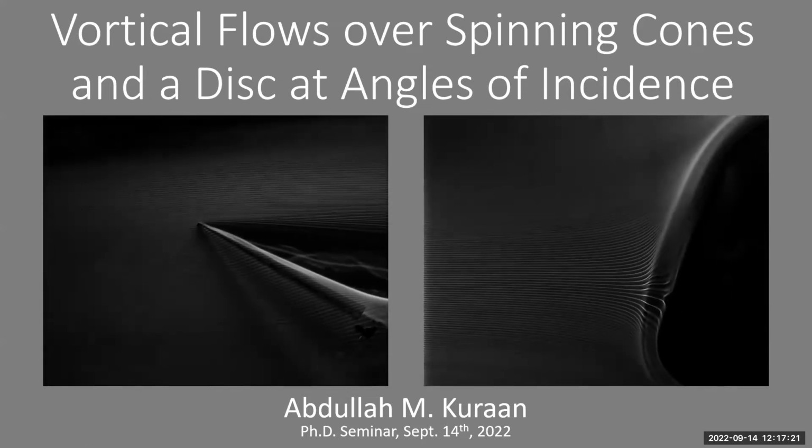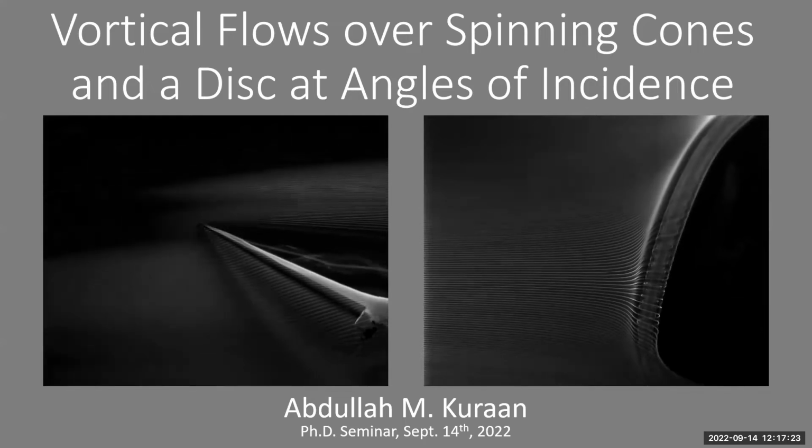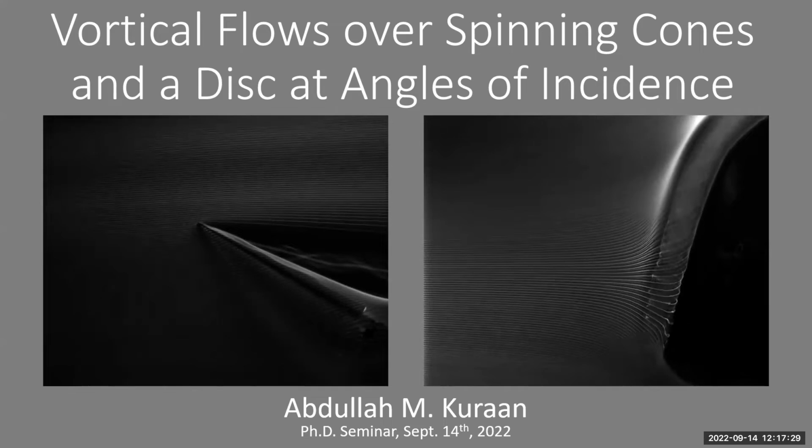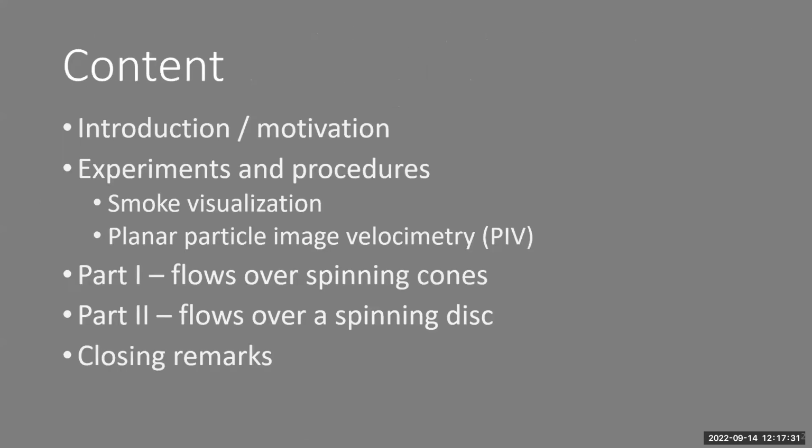Today we'll be talking about the vortical flows over spinning disks, over spinning cones, and over a spinning disk at angles of incidence. So let's go ahead and get right into it. The contents of my work are going to include some introductory slides, some motivation slides. I'll review the main experiments that we've used to study these flows. Mainly we use a smoke wire visualization technique, and we use planar particle image velocimetry to take measurements of the flow fields. In part one, I'll be presenting the results and analyses of flows over cones, and in part two, we'll be looking at flows over a spinning disk.